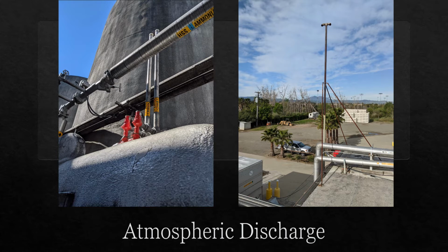If the termination point is on the roof, the termination height can be reduced to 7.25 feet if that roof is occupied solely during service and inspection. This same requirement is applicable to platform surfaces, such as condenser platforms. IIAR 9 requires that relief valve piping be configured with provision for draining moisture from the piping.